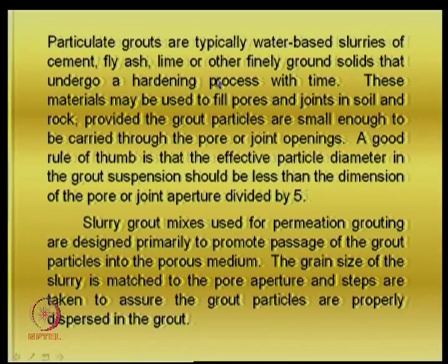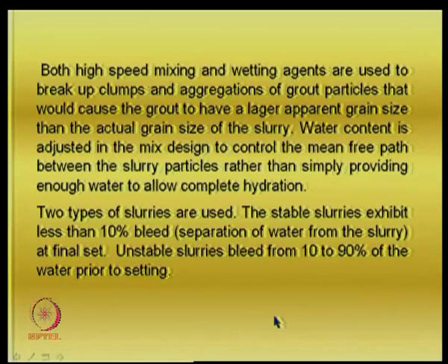Steps are taken to assure that the grout particles are properly dispersed in the grout. Sometimes you may have to use dispersing agents to see that it is stable. Both high speed mixing and wetting agents are used to break up clumps and aggregations of grout particles that would cause the grout to have a larger apparent grain size than the actual size of the slurry.